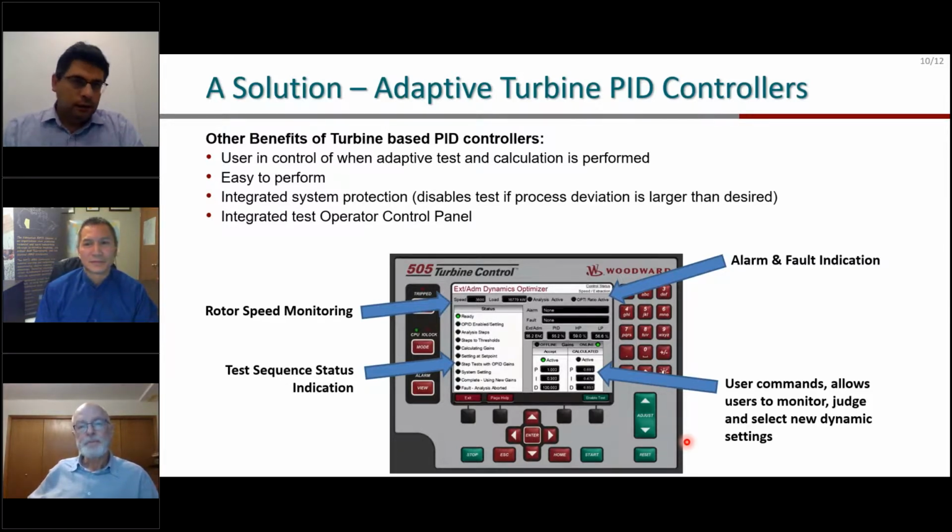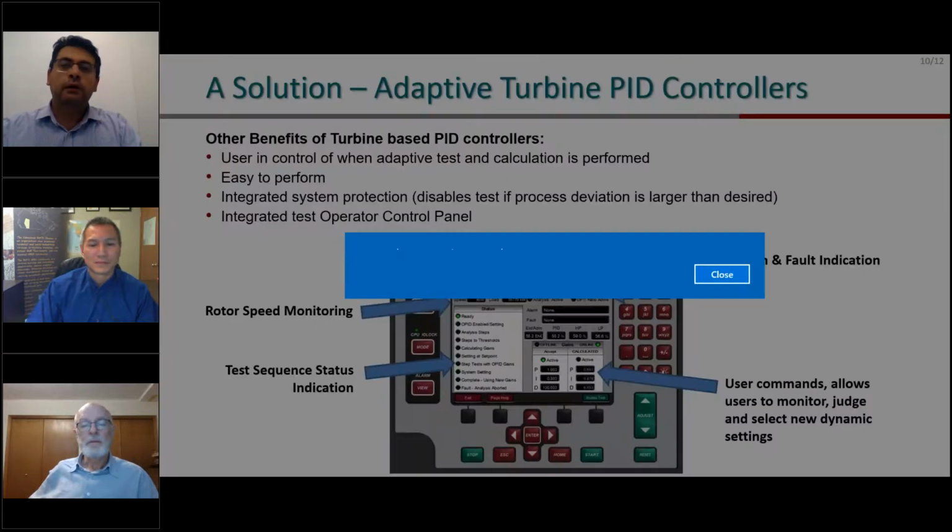So what it does is basically we have 3 different modes: proportional, proportional integral, and proportional derivative. Usually you run it with the proportional alone and see the responses of the turbine. Then you run it with the proportional integral and the proportional derivative. Usually each mode itself takes 10 to 15 minutes. So maybe half an hour, 1 hour.